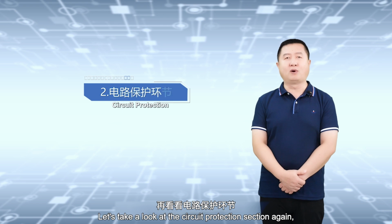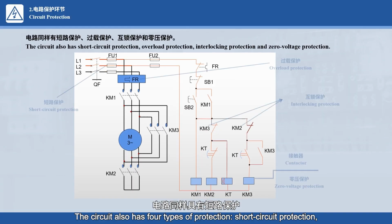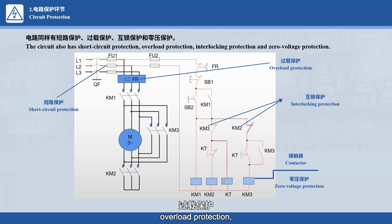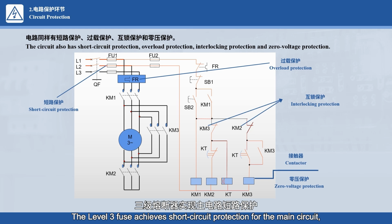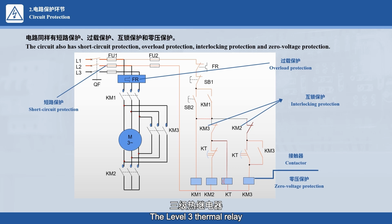Let's take a look at the circuit protection section again, as shown in the diagram. The circuit also has 4 types of protection: short circuit protection, overload protection, interlock protection, and zero voltage protection. The Level 3 fuse achieves short circuit protection for the main circuit, and the Level 2 fuse achieves short circuit protection for the control circuit. The Level 3 thermal relay realizes overload protection of the main circuit, and the Level 1 thermal relay realizes overload protection of the control circuit.